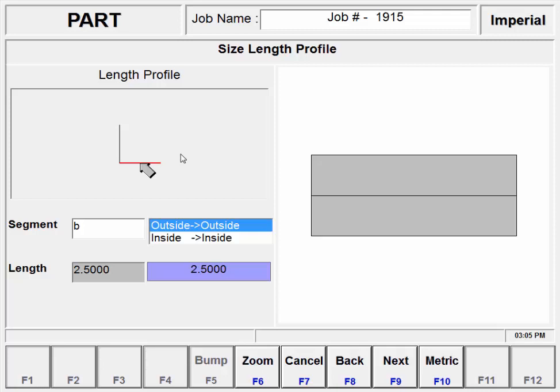What I'm going to do now is use my left and right arrows, and I'm going to hit my left arrow back once, and that's going to highlight that corner. So this corner lights up. You'll notice that the bump is enabled. You'll see this will be ungrayed. I'm going to switch off of it real quick, and you'll see how the bump is grayed out. I come back to that point, and you'll see the bump is highlighted. So now I can do my bump mode.